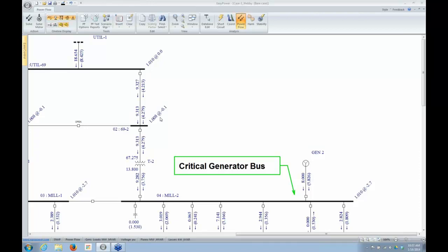Scaling the kVAR, yeah, there's not really a way to directly do that in EasyPower, scaling the power factor or the kVARs. That would be nice to have a temporary way to scale that, but right now we can scale the overall kVA load, but we can't scale the kVARs or change the power factor as a group or as a scaling factor.